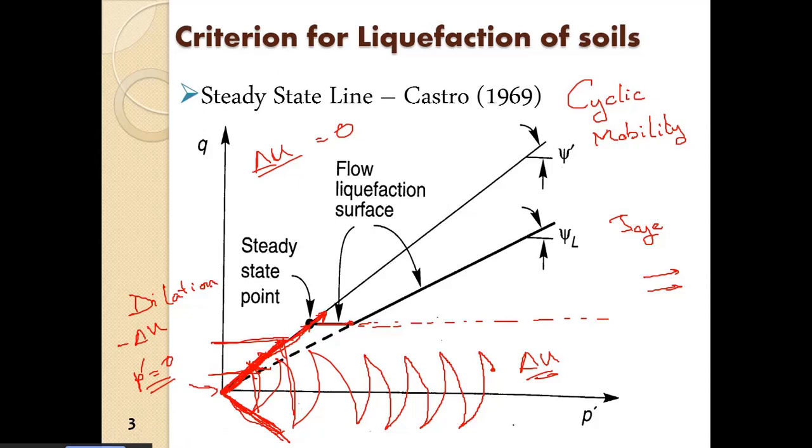So this is basically the same as the initial liquefaction state, all right, which we discussed in the cyclic triaxial test in our previous class. As we saw, the Mohr circle moved to the left and came to this point, and there was huge strain developed in the sample. So it is in the initial liquefaction state, all right, and therefore there is a significant amount of straining.